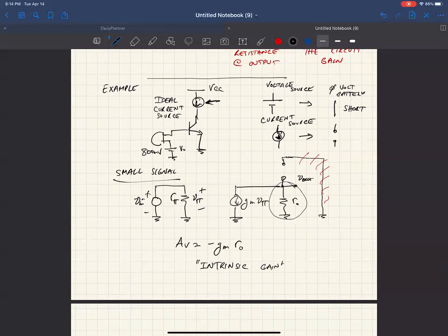And that's the max gain you can possibly get out of this device, no matter what resistances you hook up as a load. So when you buy a transistor, say, if it's a discrete component, this is just what you get. This will be defined. So you have the early voltage, and you know how much current you're going to run through it.